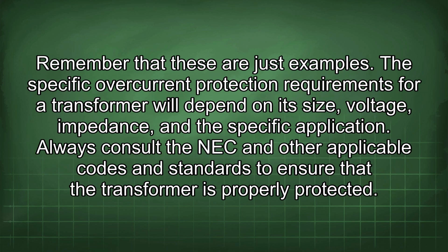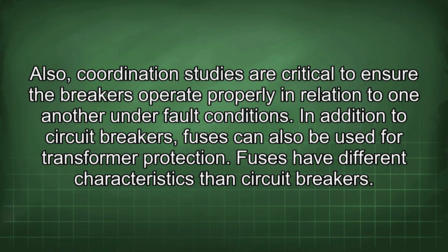Remember that these are just examples. Specific overcurrent protection requirements for a transformer will depend on its size, voltage, impedance, and the specific application. Always consult the NEC and other applicable codes and standards to ensure that the transformer is properly protected. Also, coordination studies are critical to ensure the breakers operate properly in relation to one another under fault conditions.